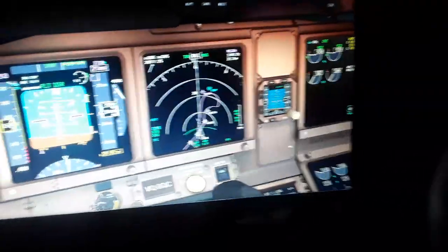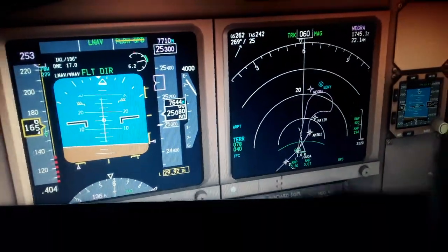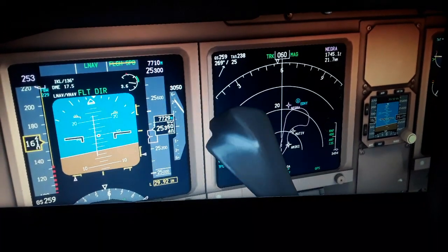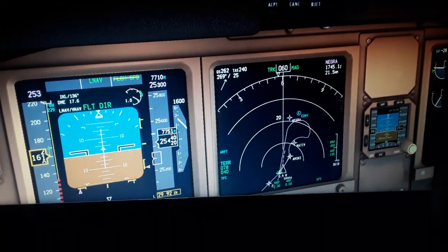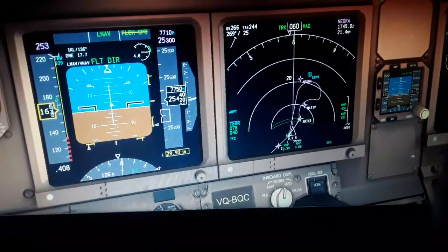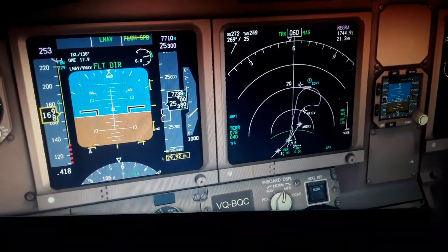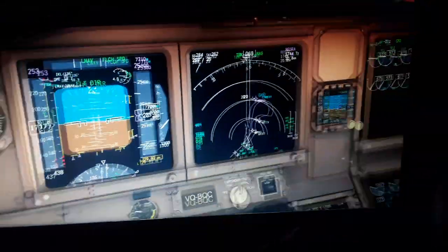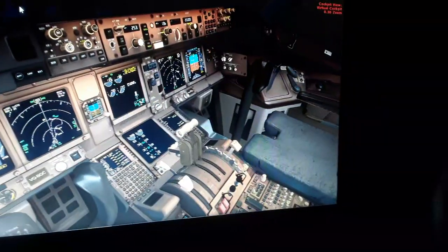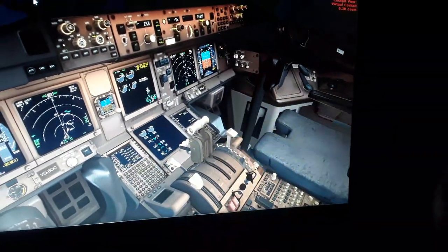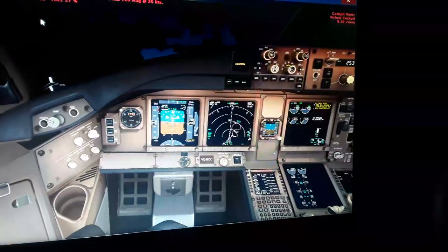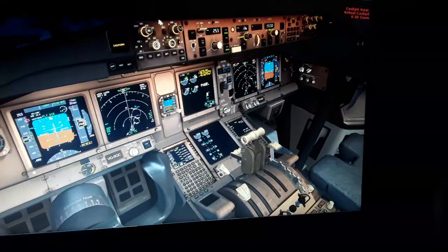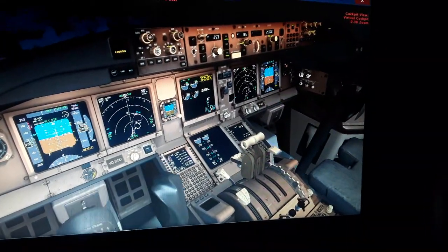So now we reach the climb cruise altitude over here, 35,000. We need to pitch down a little bit, leveling off. Also this increases the airspeed, as you can see. Retract also the flap and hold the manual over here. Also maybe we're gonna increase the airspeed.